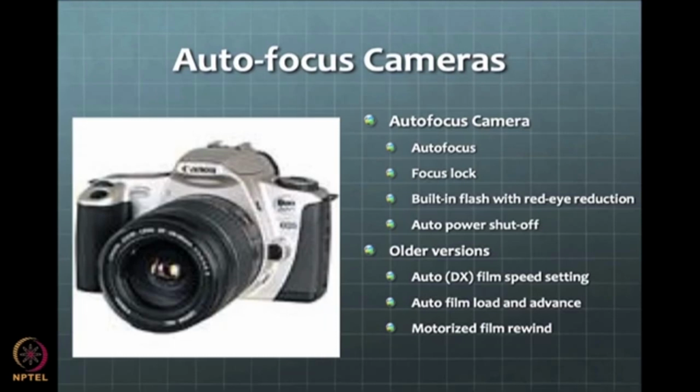You can shoot a light, or rather an invisible ray, that goes from the camera to some object, and from that object the reflection of this ray comes back. You sense it and gauge the distance, and once you have knowledge of the distance, you can adjust the lens accordingly. But that is again somewhat of a feedback system, where the intent of the user may not get captured.